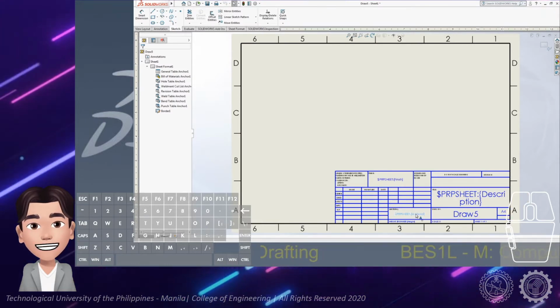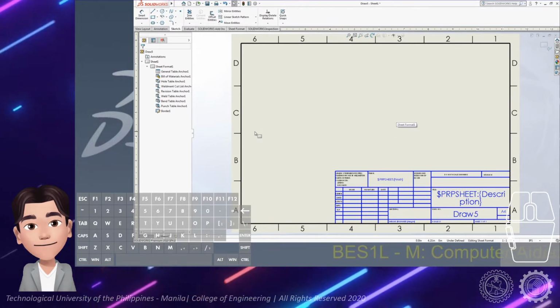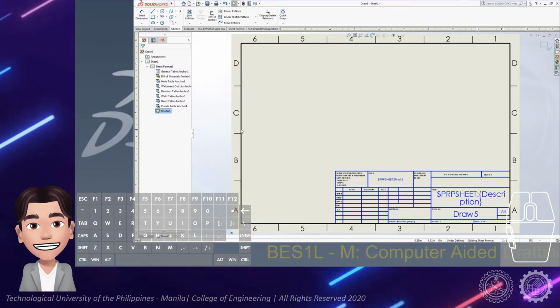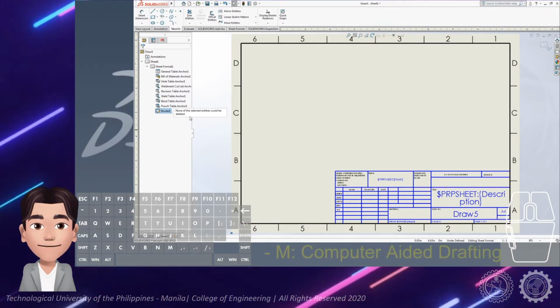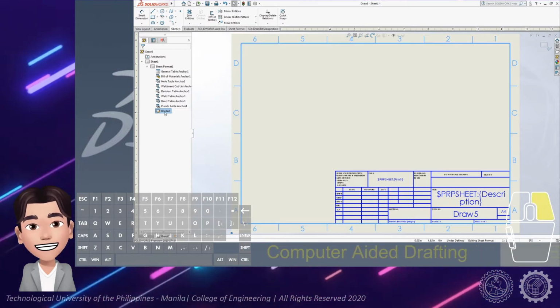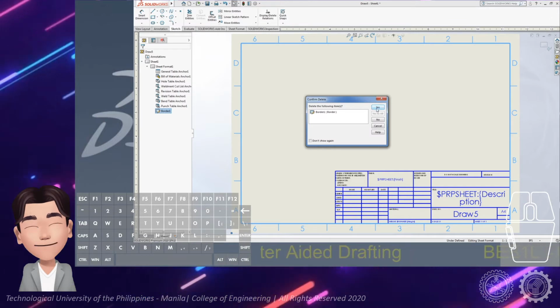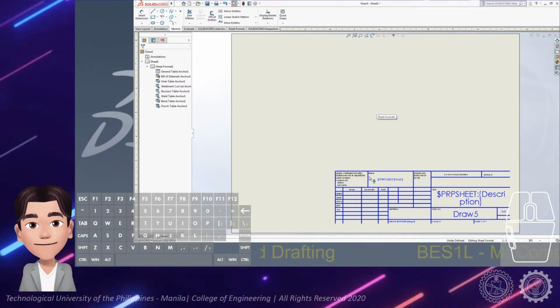Press a line or a text and then click Delete on our keyboard. Click the border and delete, but nothing will happen since it is locked. All we need to do is to press right-click on the border title under the sheet format on the left side and click Delete Border. And press Yes, then the border is gone.